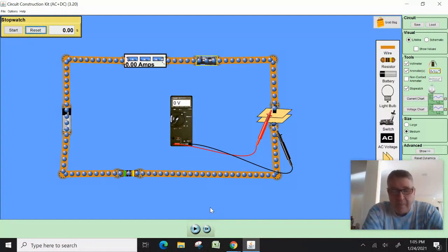It's a long time. And so for this circuit, because we have a 50 ohm resistor and a 0.2 farad capacitor, our RC is going to be 10. Therefore, if I run this for 50 seconds, the circuit will be done in the 50 seconds. Now, one thing to note is the clock on the stopwatch is not the same as a real clock. So the 50 seconds in the simulation is not 50 seconds in real time. It's a little slower. So it's probably going to be 100 seconds in real time. But it's calibrated to the circuit, so it's actually correct for the circuit. So we'll let it run until it says 50, and you'll see the pattern here.